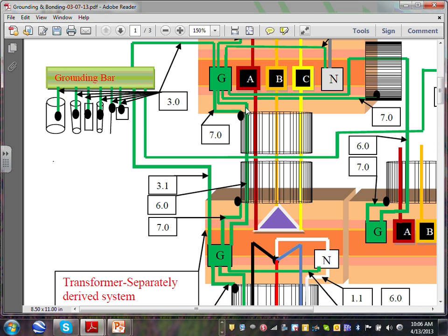If you tie it the way I said, on both sides, the same wire acts as your equipment grounding conductor and your equipment bonding jumper on the load side, because it bonds the conduits, the flex, on both sides. Any comments, guys, about that one?